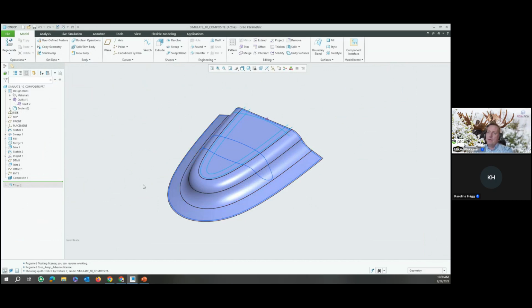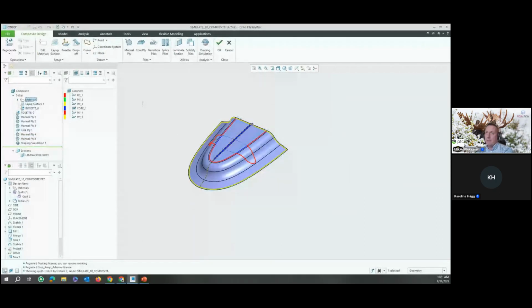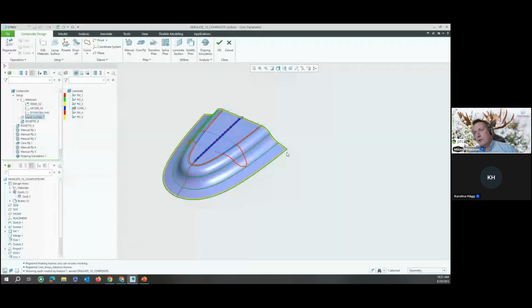And if I take a quick peek at this composite tool, you will find Engineering Composites, if you do have the license, you go and just say, okay, let's define some composite material. And how it really goes is that you have to have some composite materials in your models. With the recent Creo installation, you do get some sample models for you. In here, I have a few fun fabrics and one foam material, which is in the model. After that, you define the layup surface, so basically a quilt where you start modeling.